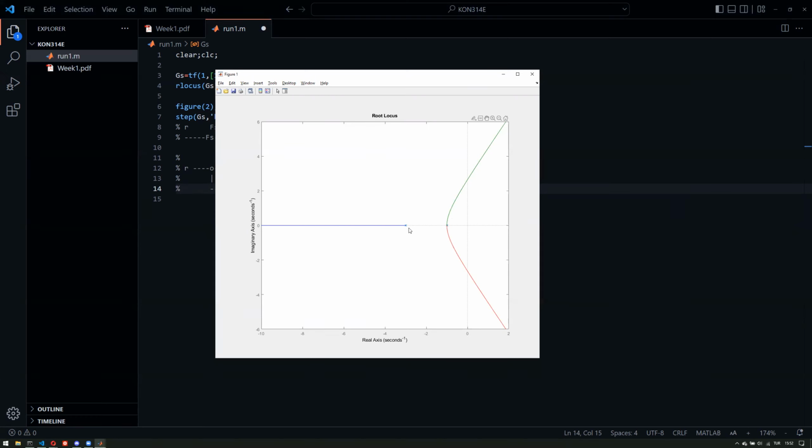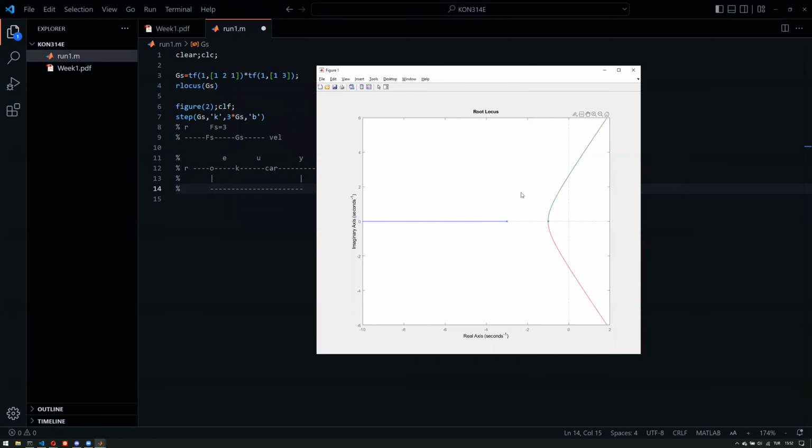Now, I can see that the 2 poles will get closer to the j omega axis. And the closer they are, the slower the system becomes. So for this system, if I have a certain k and increase that k, the system will become slower. The third pole is going to the left, which should be a fast mode, but it will lose its effect because it's going far away, and these are the dominant ones.